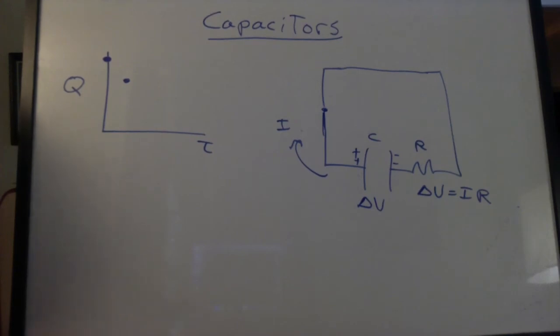As the charge flows out, the voltage drop on the capacitor is reduced. Therefore, the voltage across the resistor is reduced, and the current will be less. You will not lose as much charge in the same amount of time. And the process continues.